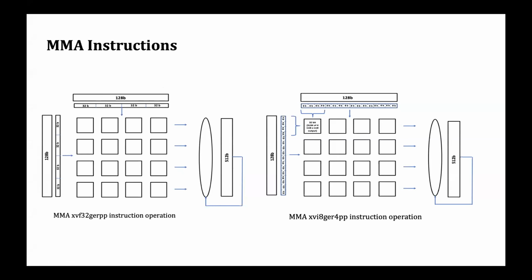So in order to handle this 512-bit result, you might ask how you will hold the 512-bit results now, since our register file size is only 128-bit. The solution is pretty simple. We mapped four 128-bit registers to represent one 512-bit register or value. That way the result gets into 4 different 128-bit registers, so you can operate on those values separately or as a whole, as one single value. That way we were able to address the output requirement as well, and we were able to do this for various different data types, all the way up to 8-bit.